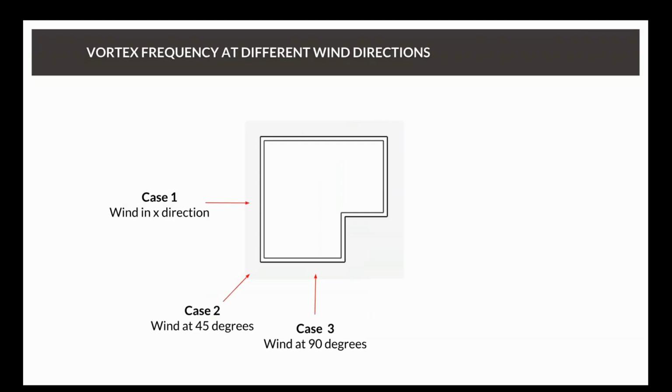We're going to run 3 different studies. Often in wind tunnels, you might run 36 different wind directions, so every 10 degrees around a building within a city. You can do that too, and I'll show you in a second how to do the different directions and rotate the CAD around very quickly without having to change anything outside of SimScale. We're actually just going to run 3 directions and compare them again side by side. So we have the first case where the wind's coming from the left, the second at 45, and the third case where it's coming from the bottom.